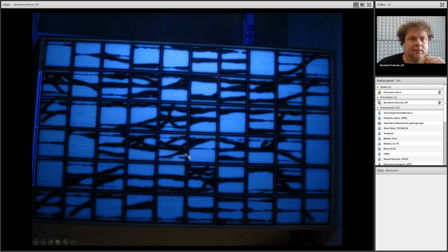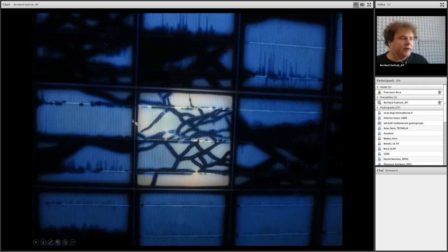Here you have a lot of cracks in this module. Not sure why, probably snow load or mechanical load testing, I don't remember exactly, but you see a lot of cracks. What you can also see here on the left side, maybe a bit weak, is that there is a second sheet behind the busbars that is typically put in to have isolation in the section of the junction box, at the collection of the wiring, basically. If you look at a hotspot cell,